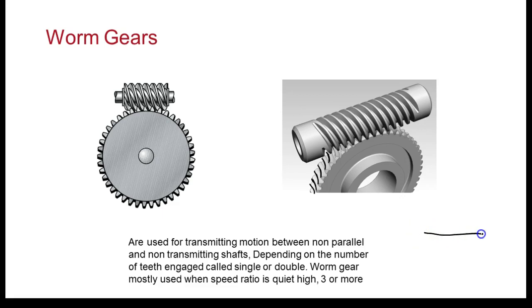Well, the problem is if these two things were straight, and I need to put them together, and this here is curved, then you'd only be making contact with very few teeth. But if we groove this thing or put a channel down through it, then the worm can come in here and go further and engage more teeth.